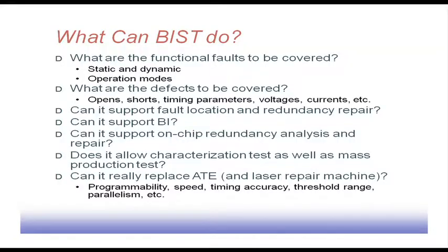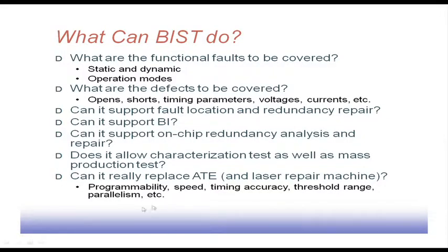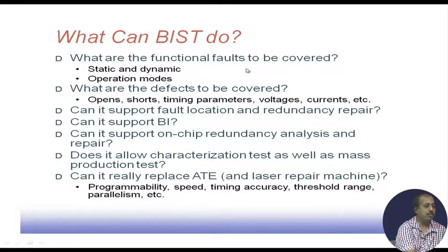So, BIST is a better option for memory testing, because BIST can be integrated with the memory itself, and once it is signaled to start testing, it can go on doing that. It can generate the patterns as per the template, the read write requests, and it can check whether it is okay or not. So, ultimately it can result in a go/no-go solution telling whether the memory chip is okay or not. So, what are the issues in BIST design? First of all, what are the functional faults to be covered? So, which faults are you going to cover?